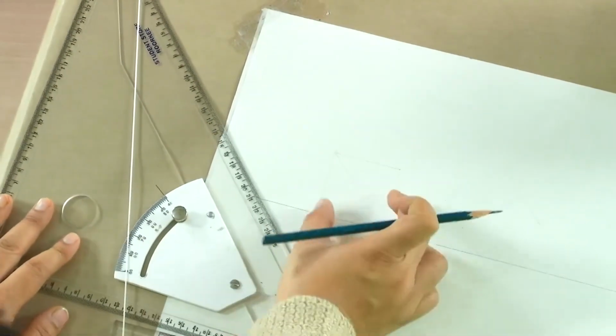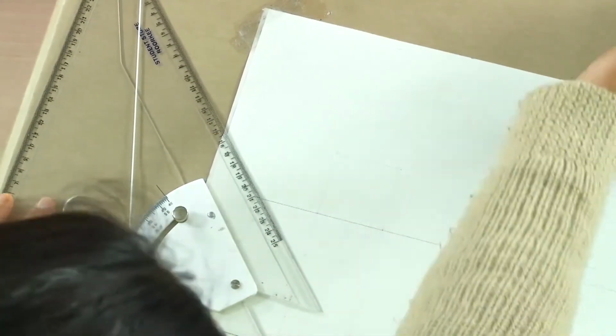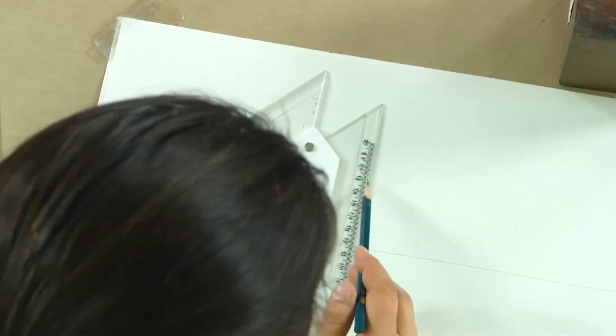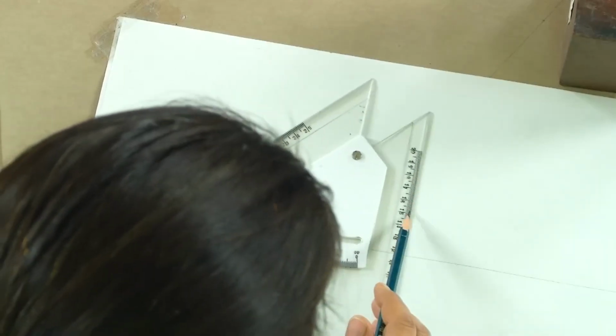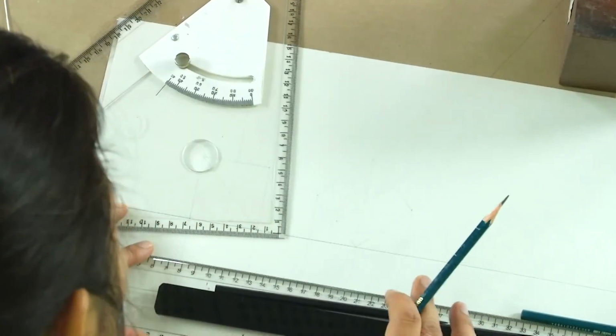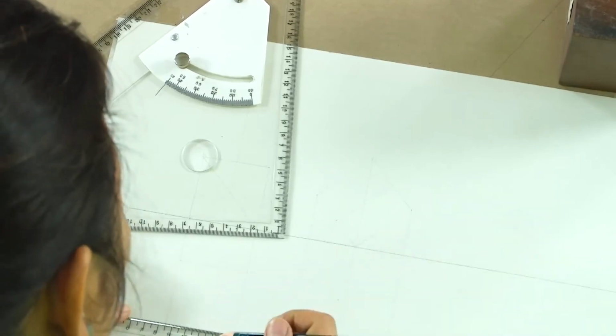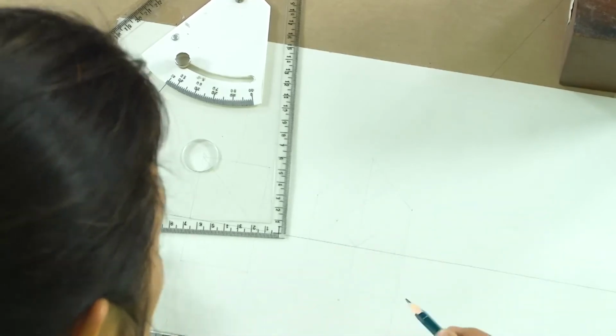This same square, this face which will be seen from the front, is now inclined at 45 degrees to HP, because this face was also parallel to the axis, and now when the axis is inclined at 45 degrees, this is what we see. Now what happens in the top view? We see two of the faces being visible now.